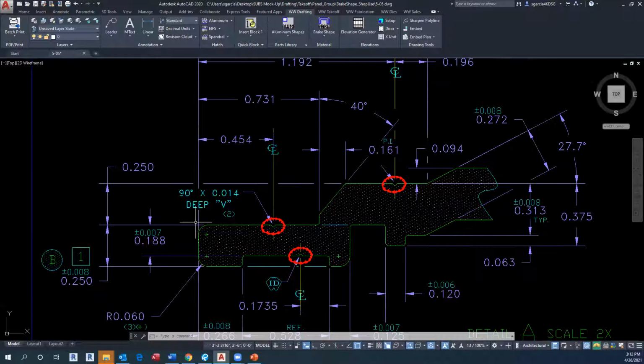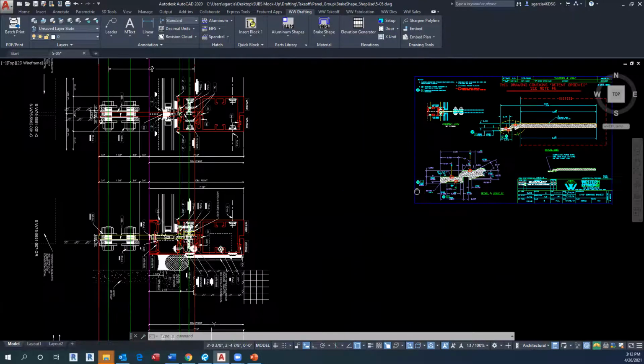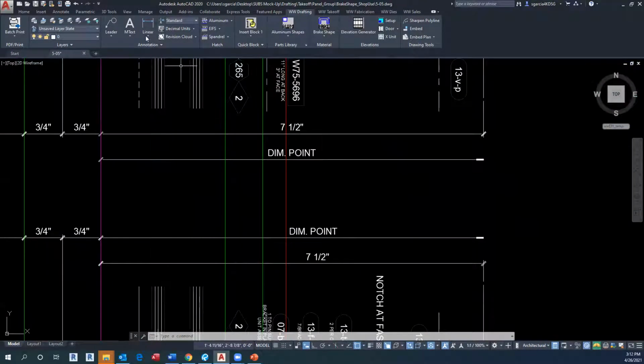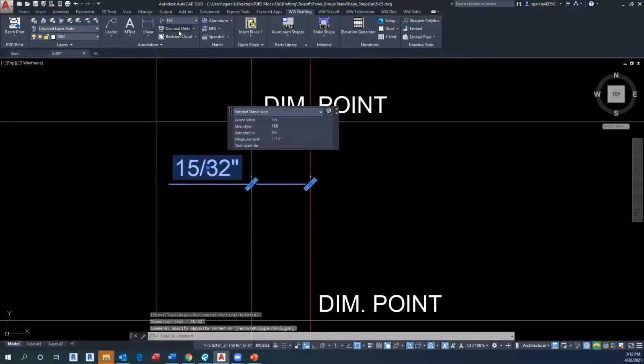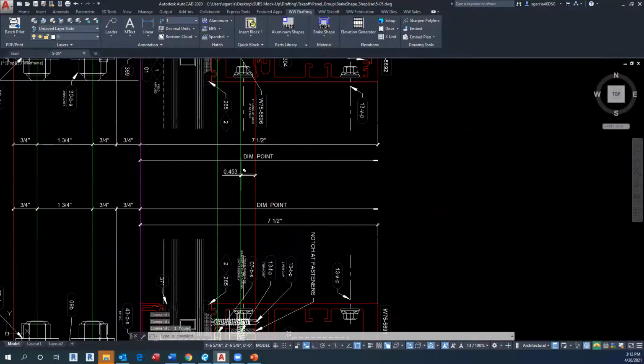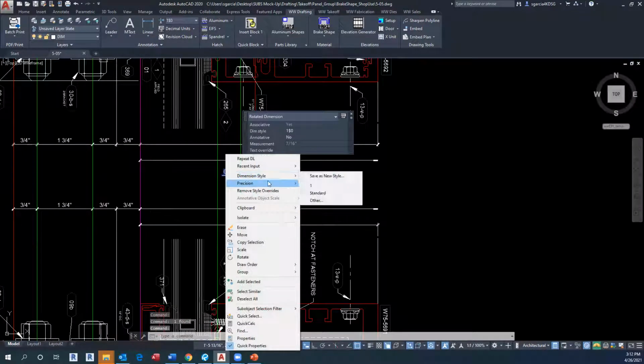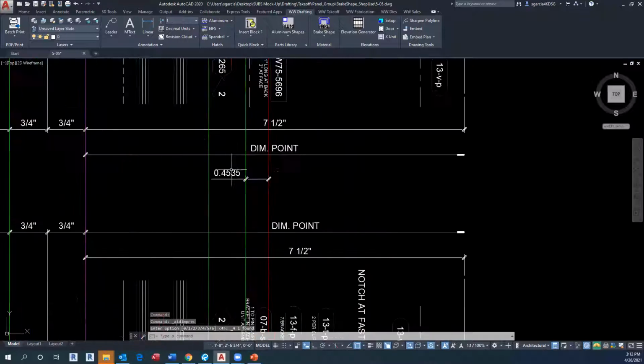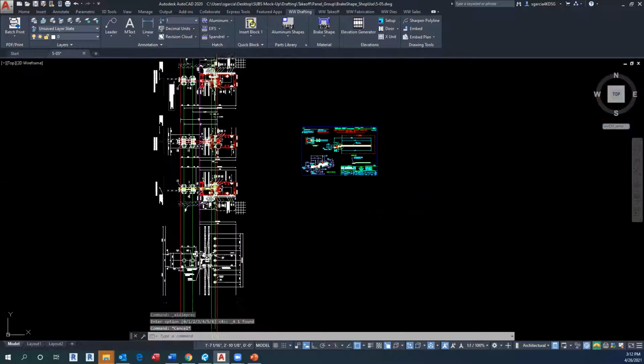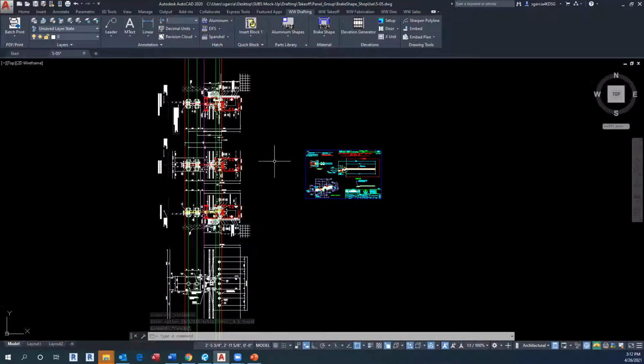For example, I have from the back to the first hole 0.404, and I can verify that if I make a dimension from the back of my part to the first hole and use decimal dimension, I have the same matching, with the difference of the precision, which I can adjust. There you go. So this is a proper way to create a layout. I need to do this not only with my sunshade brackets, but with all my shop-used project shapes, for example caps or steel bars.